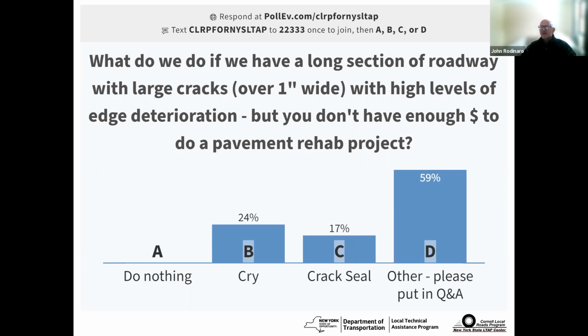Absolutely. I'd say microsurfacing is probably a little on the outside edge of this. I don't think I'd try to tackle it with microsurfacing with those big cracks, but mastic definitely an option. And then any of the more extensive repair type efforts also need to be considered.